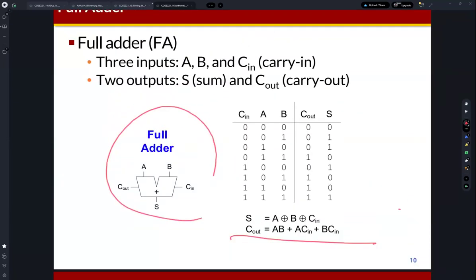Okay, that's it. So actually it's simple. If we just focus on the 1-bit operation of the addition, then we can just build the half adder and then full adder. Okay, but we use multi-bit signals, right? Because we want to represent very large numbers with multiple bits, right? So actually the arithmetic operations are performed for multi-bit data. So which means we need to build the multi-bit adder, right? And how?